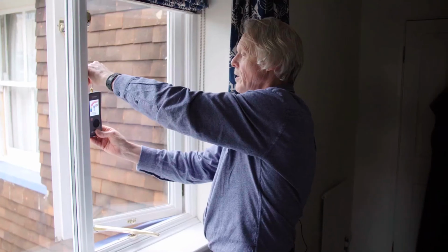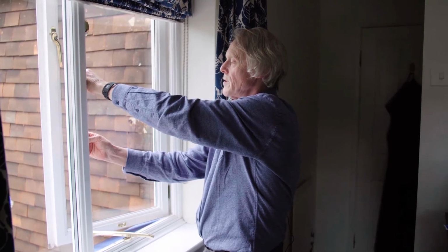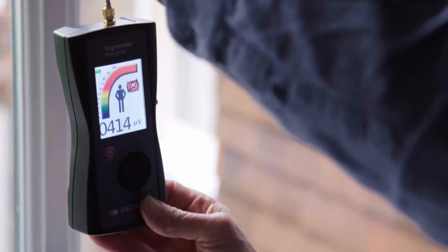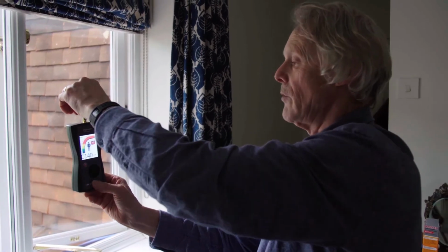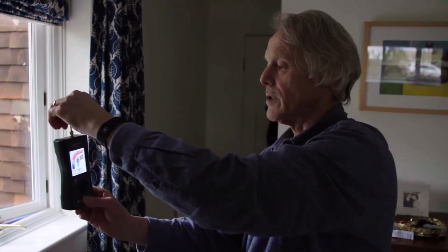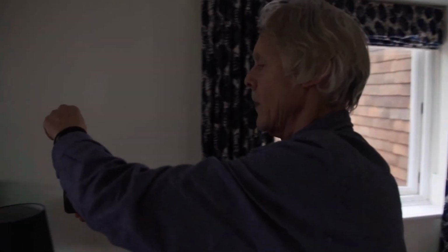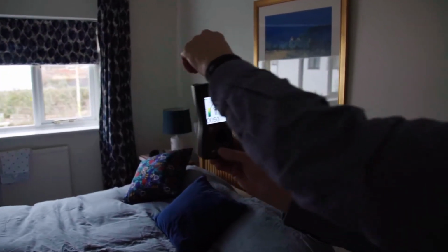But the important thing is to see how effective it's been. So now I'll take the readings with our high frequency meter. As you can see, we've got readings of around 900 to 1000 microvolts at the window. And then as we come inside the room, because it's shielded with the paint, it drops off quite rapidly. It's down to 100 here, 80, 65, and around 50, 60.